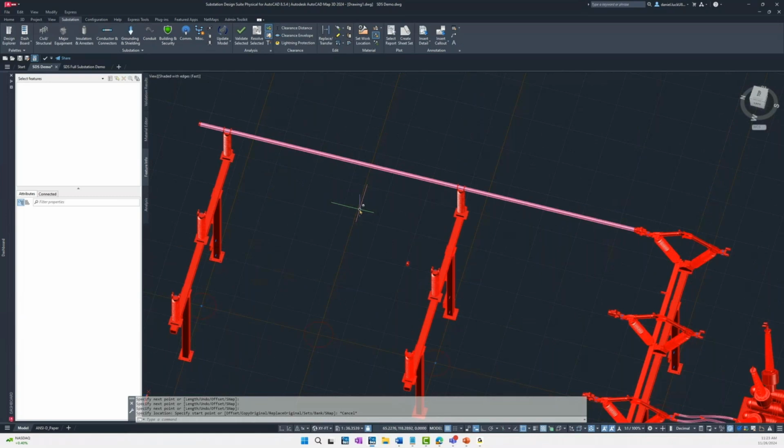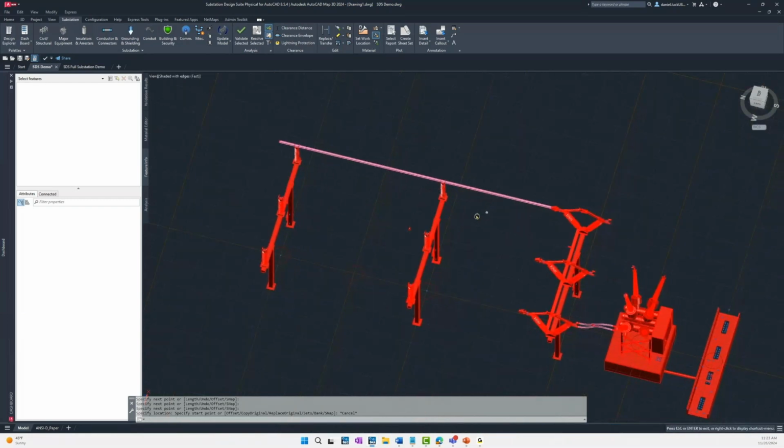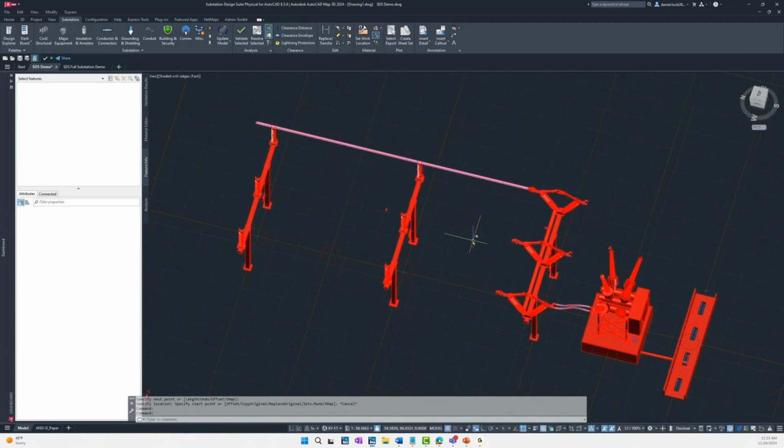So SPS does recommend designing small, and with the AUD copy and paste command. As you're working through your design, especially in greenfield substations, you want to make sure you build in small, repeatable chunks, verifying your design is 100% correct before using the copy and paste to make sure that you're bringing over the correct model data before continuing on. So now let's talk about adding additional data to the features.